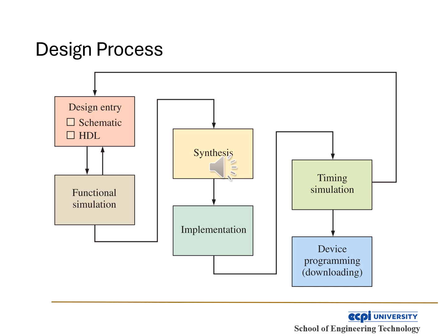the design. When it passes simulation, we go to synthesis. Here, your abstract design gets turned into actual digital logic that the FPGA understands, like translating your house plan into materials and measurements. Then comes implementation. The synthesized logic is placed and routed inside the FPGA layout. Now it knows where everything lives, what connects to what.